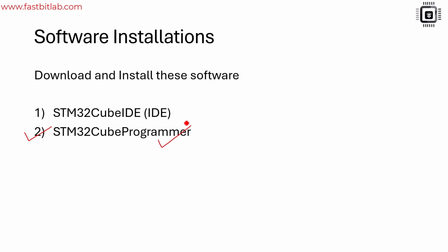But if you don't have any debuggers with you, you just have a custom STM32 microcontroller board which doesn't have an onboard debugger, or you don't have access to an external debugger, then still you can program the board using this STM32 programmer, because it can talk to the bootloader of your custom hardware and download the executable to the target board. For that purpose, we'll be installing this software.